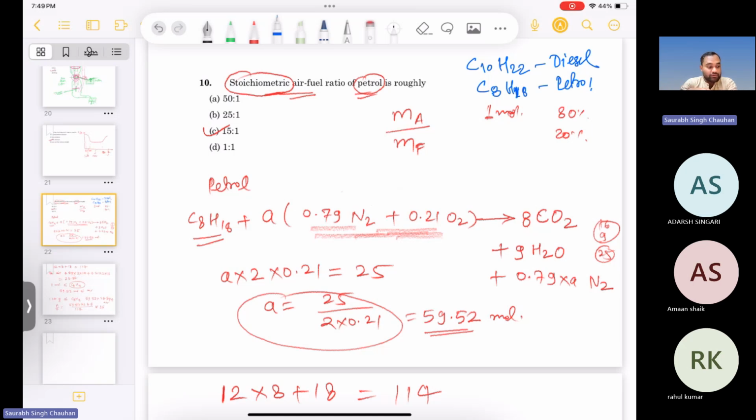But in your Dulong formula, it is only depending on the number of atoms, right? So can it be correct? No. So it can give a rough value, but exactly how much energy you will get after burning 1 kilogram of fuel depends on a lot of parameters. So what is the bond structure, how these atoms are joined together, whether they are a normal chain or iso, right? Yes, sir. In chemistry, you have studied IUPAC names. So how they are combined, right? Yes, sir.